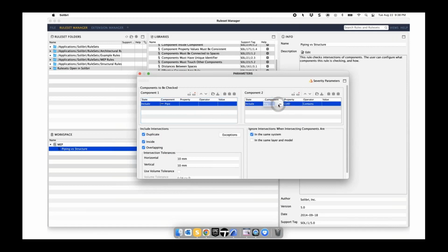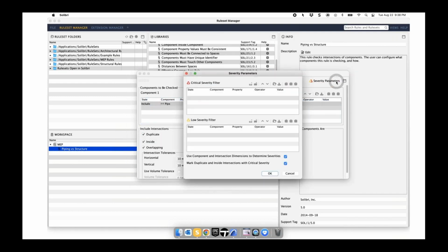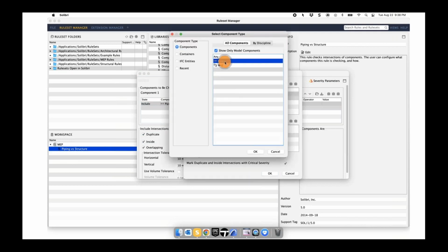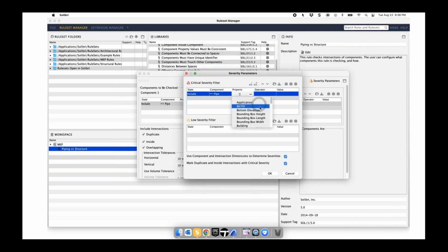Again, you can get as specific as you want. I put walls in there. Oversimplified, you probably want other things in there. But now we're going to say for high severity, that the pipe size must have a width that is, see what I did, greater than or equal to 50 millimeters. And we're going to say that for the pipe size, for a low severity, it's going to be less than 50. It's still going to report the data,